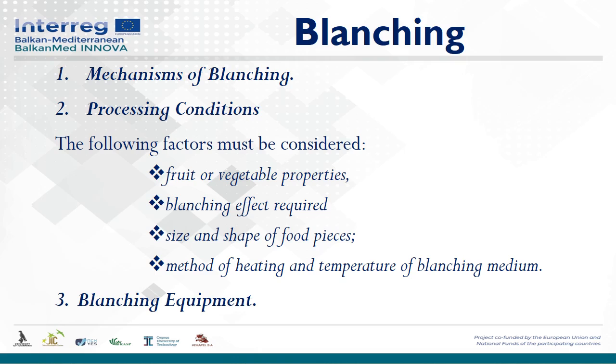The raw material handling conditions for the blanching process are intended to minimize nutrient losses, degradation because of high temperature, etc. In general, practice has shown that steam blanching systems can cause less loss of nutrients compared to immersion systems. The time and temperature during blanching should be kept at those values where they can provide a balance between maintaining the quality characteristics of the raw material and avoiding overprocessing.